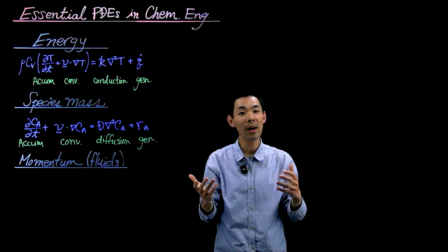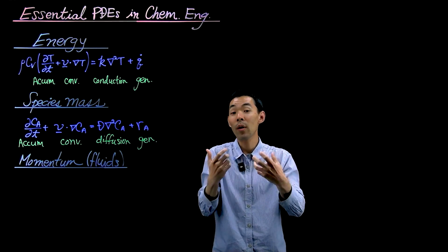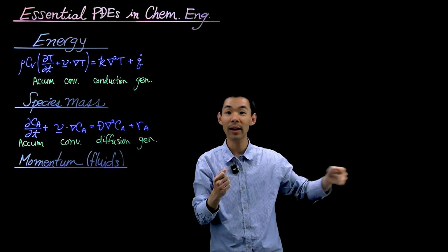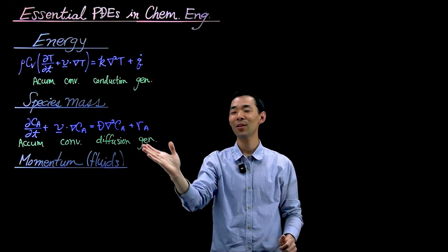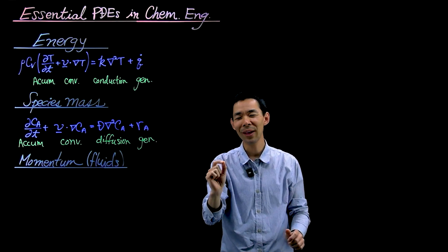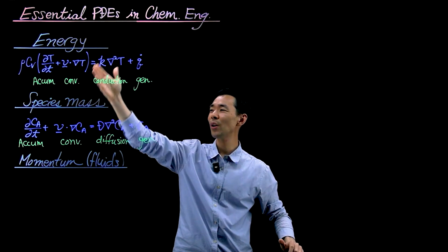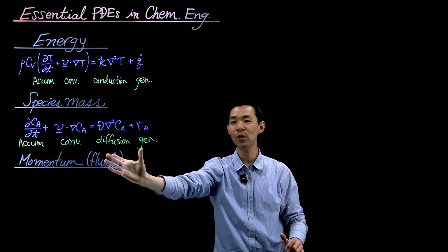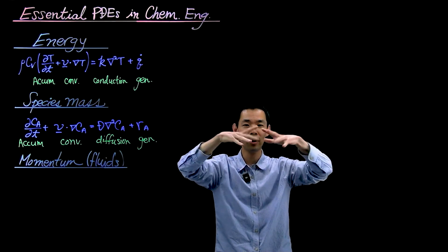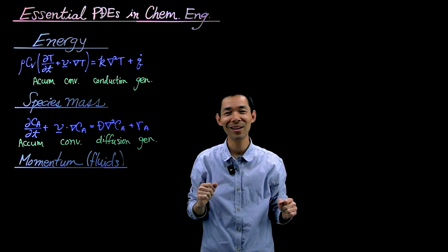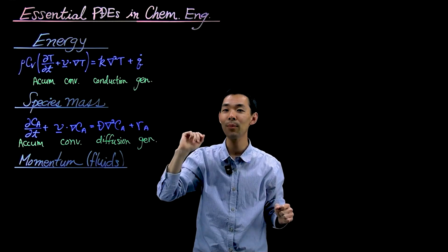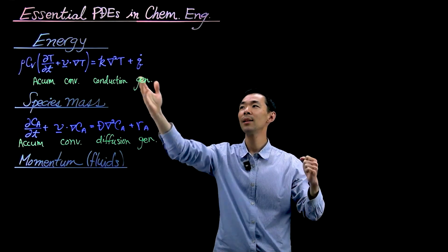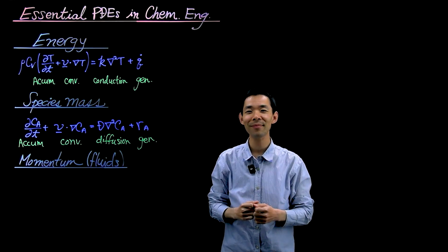So that also is obvious. You have generation or sinks of reactant of species A if it's becoming products, right? So we need to include a generation term. But morally, it's the same classification: accumulation, convection, conduction or diffusion of some sort that seems to blur out variation in your density or variation in your temperature profile. Lastly, some generation of species mass, some generation of energy.